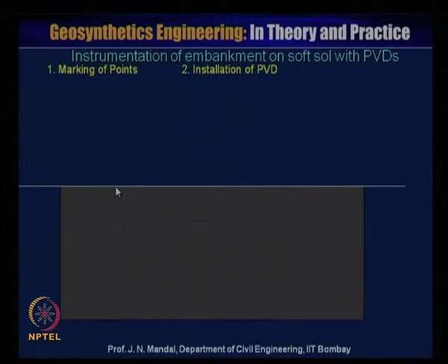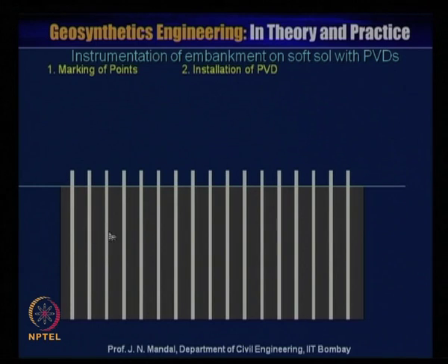Initially there is this marking point, and then you have to install the prefabricated vertical drain like this in the soft soil foundation, at a particular spacing, and you know how to calculate the spacing between two prefabricated vertical drains.